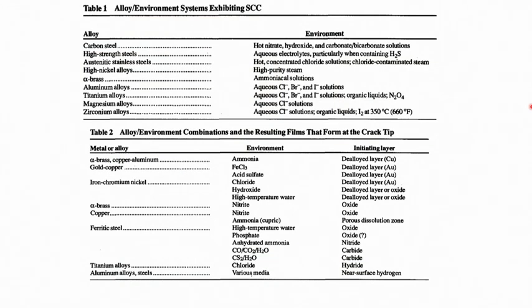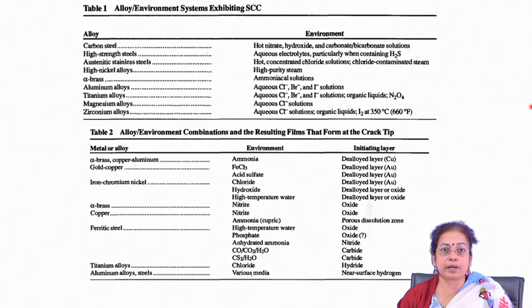As I mentioned, stress corrosion cracking is very much environment specific. All alloys do not undergo stress corrosion cracking in all environments. These are the environment-material combinations where stress corrosion cracking behavior has been observed to date. But again it is a very open field. For many alloy environments, the environment in which it undergoes stress corrosion cracking is not known, because this observation is also very painstaking.